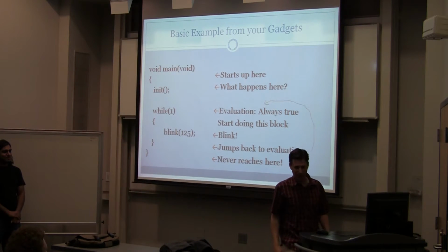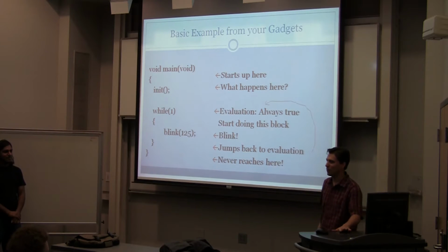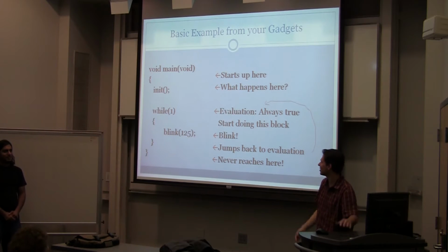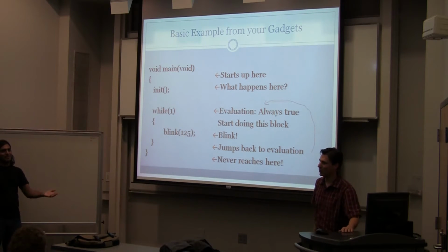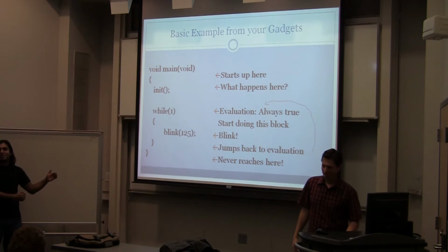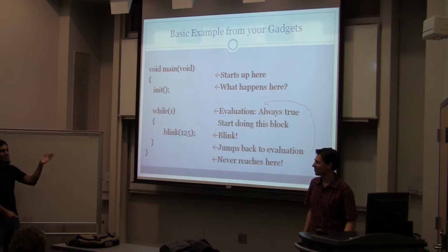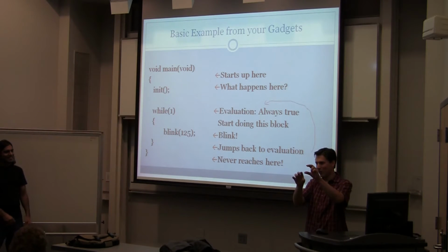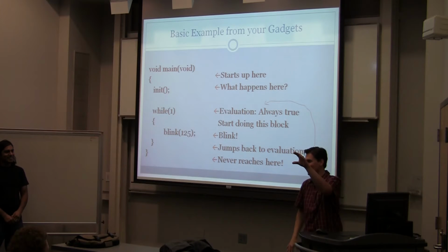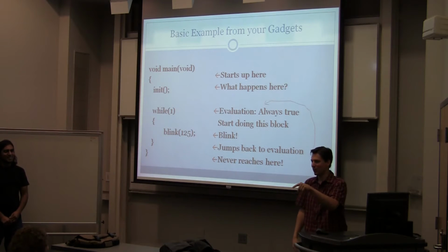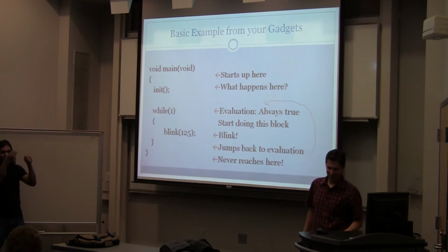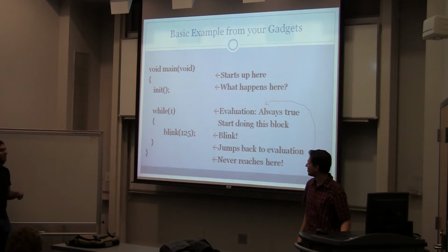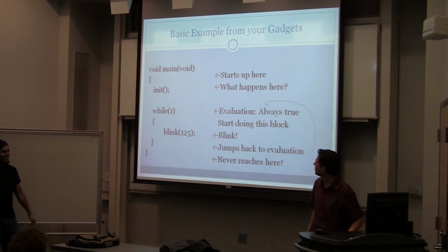If you're familiar with programming in general, you know that infinite loops are bad, but with microcontroller programming, infinite loops are good because there's no operating system. If you exit your program, basically nothing useful happens. It just reads right off the end of your program and starts executing random stuff at the end of memory. So if you have a small program that you program over top of a bigger program, it can actually go into the bigger program. It'll just read right off the end. Like think of if you cut out a small piece of paper and pasted it on top of a bigger piece. It'll just read right off into whatever you're doing. So you always want to have an infinite loop, basically.